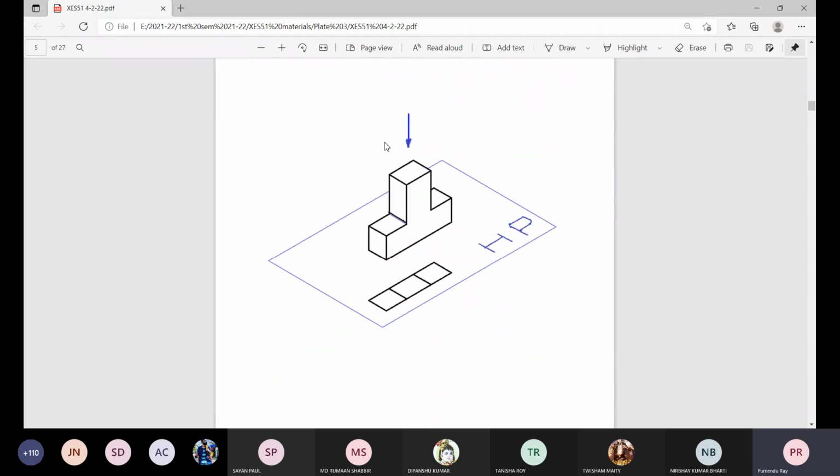Similarly, when we see from top, that shadow formed on the horizontal plane, it is projected on the horizontal plane named as HP. It is another thing. Now these two are the primary idea for projection of any object on perpendicular surfaces with lines of sight parallel to each other. And for any such object, for its description, we take the help of this method, which is called the orthographic projection.